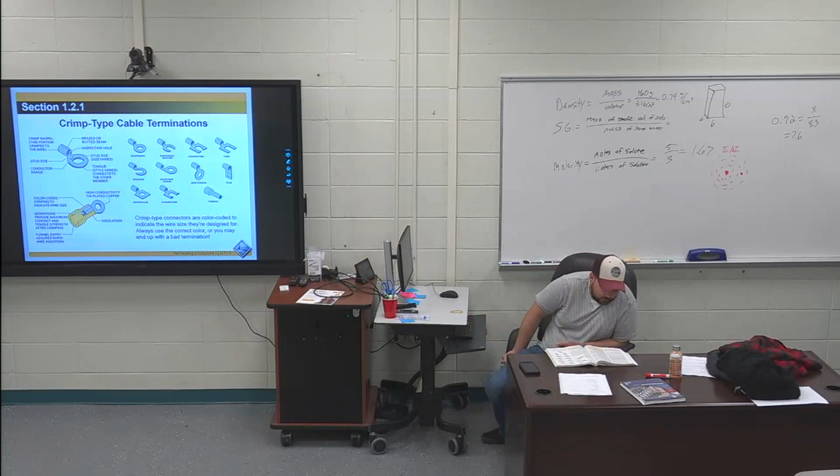120, low voltage connectors and terminals. 121, crimp connectors for screw terminals. This might seem dumb. Everybody's probably put on some of these crimp connectors before, but there is a correct way and definitely an incorrect way of putting these on. My highlights for 121, second paragraph, first sentence is highlighted. One disadvantage of indenter or crimp connectors is that special tools are required to make the joint.